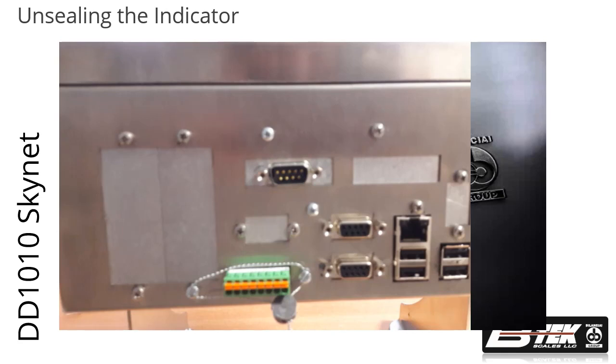The sealing screw next to the RS-232 port has the calibration switch behind it. To access it, remove the screw and then use the small tweaker or paperclip to press the button.